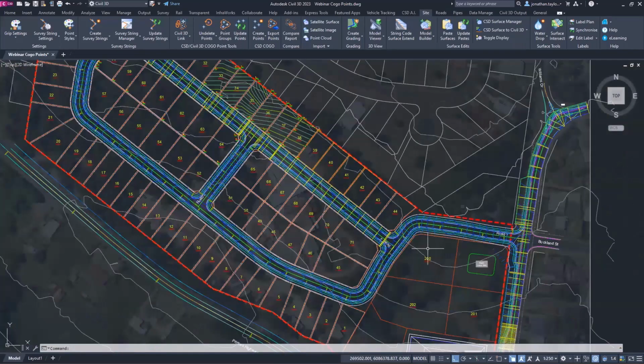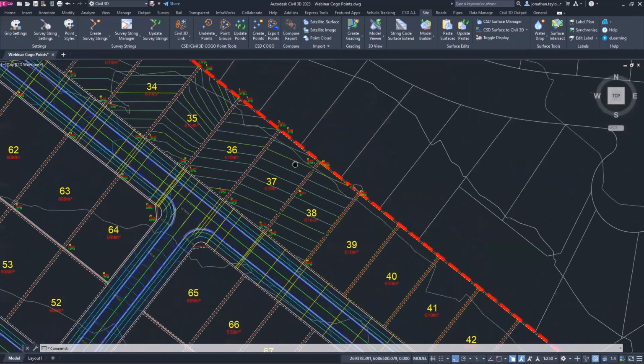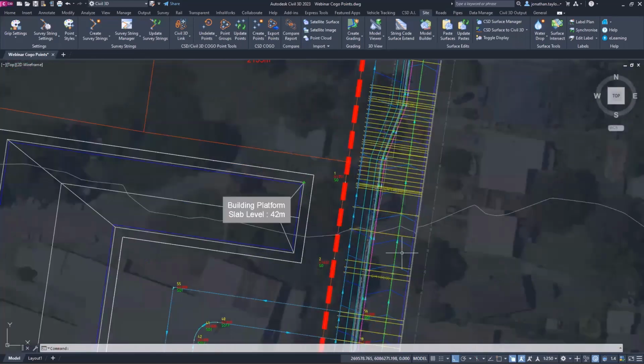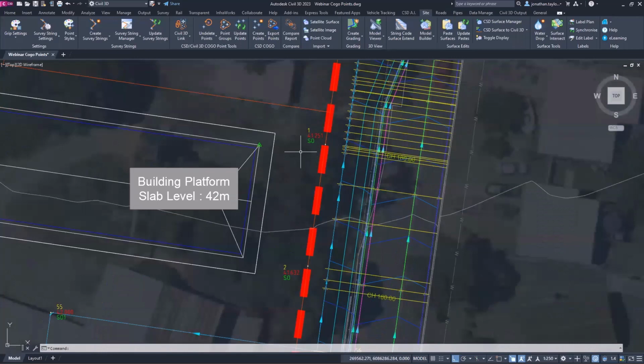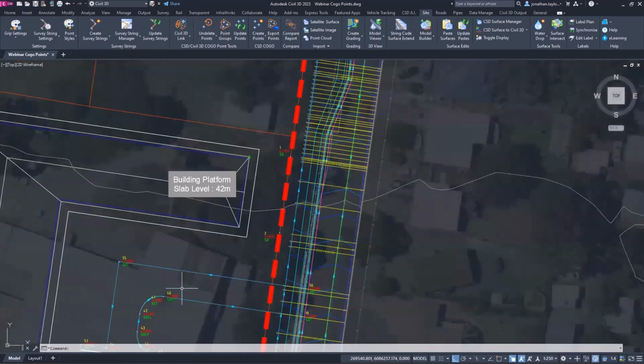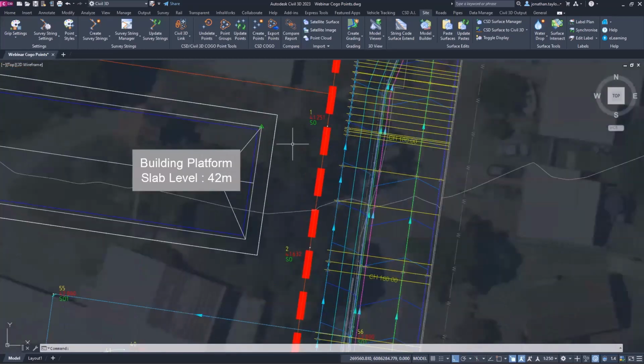So now I've created this, we will look at Model Builder shortly. I just want to show you another example of how you can incorporate these for those guys that aren't specifically doing lots. This is an example of a couple of Cogo points I've created manually, and you can see I've put them in a group called SO. So I don't want them to be picked up by my lots or anything to do with that lot group. SO just stands for set out.